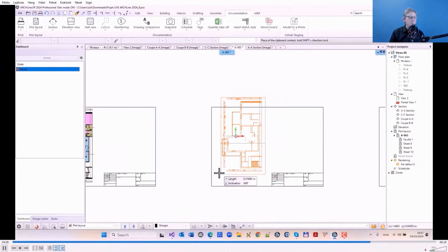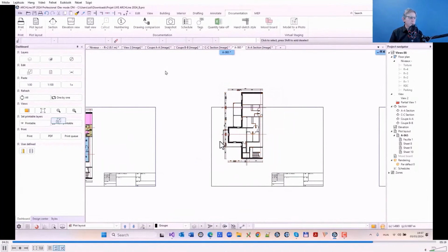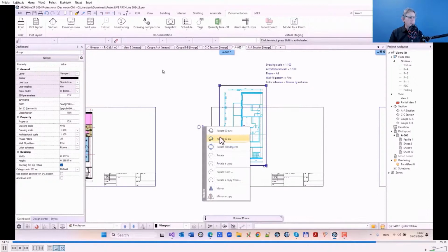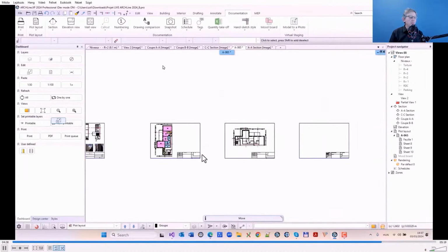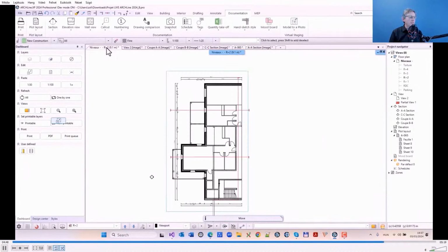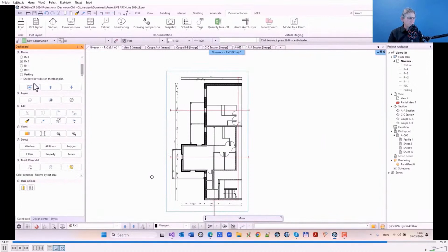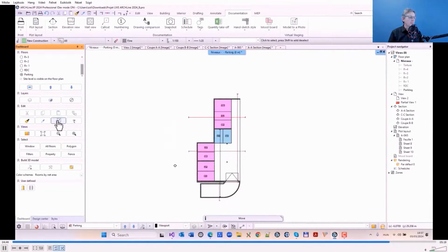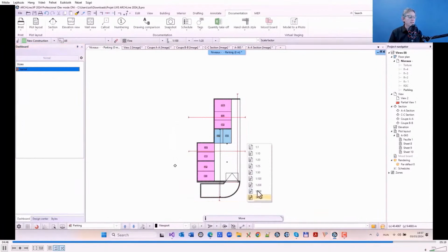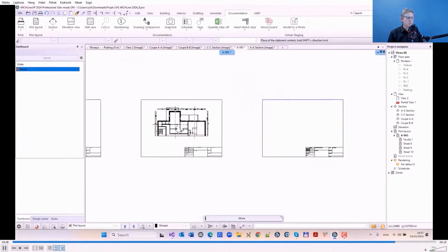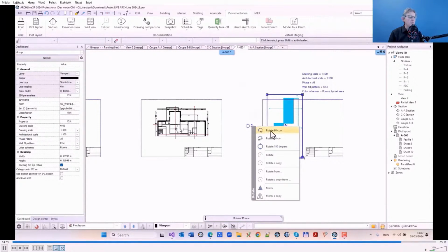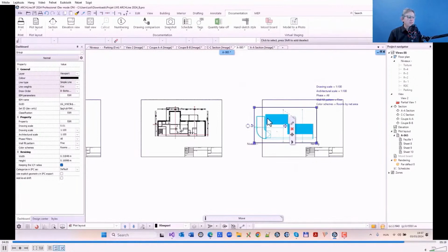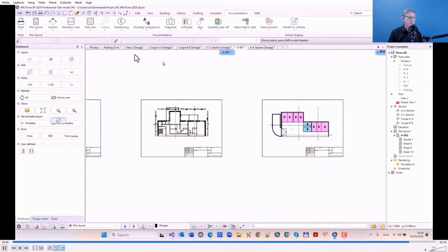Now let's see what about the new command, the viewport. The viewport is a very quick and easy way to construct your print layout. In any view, for example in the floor plan, or you are working in a section view, you can start and use this new command, the dashboard, and you can place the selected content onto the print layout with the required scale factor and other parameters as well.